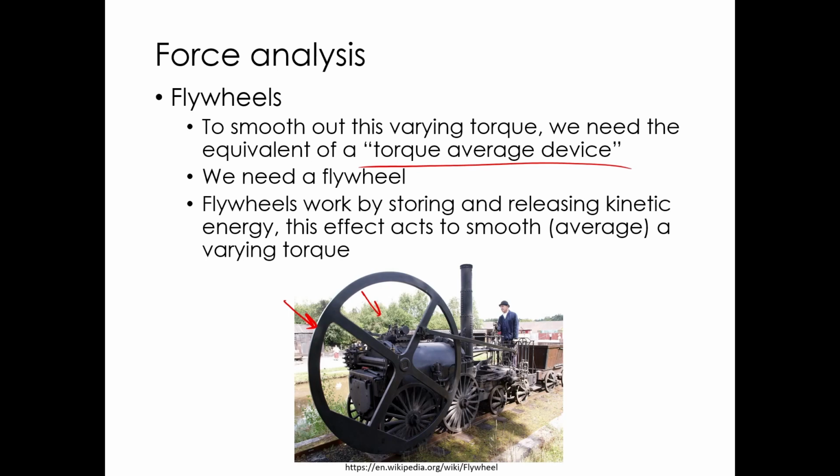And this is true when you think about small gas engines, like a small 5-horse Briggs and Stratton engine or something like that. If you look at those, they've got a big flywheel on them. They've got a big chunk of cast aluminum that serves a lot of purposes, but it's a flywheel for the crank. Usually also is a fan for an air-cooled single-cylinder engine, and it's also the ignition timing system. It'll have a magnet that's spinning on it, and there'll be a magneto that the magnet goes past, and that causes a spark.